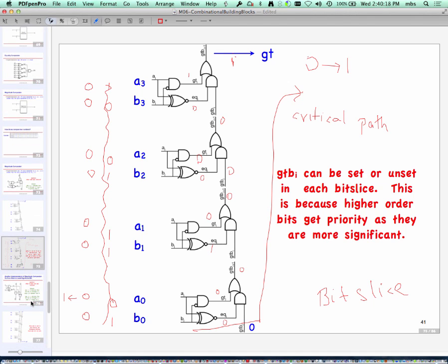So I think the critical path should be from the B not input, B0 input to the output. That is correct, because the XNOR usually has a longer delay than the AND structure. So the critical path actually would correspond to a change out here affecting things. Okay, but I was glossing over it. I was basically assuming that these two have the same delays. But you're right, there is one more gate. My point here is going with this long path which is straddling all the bits.